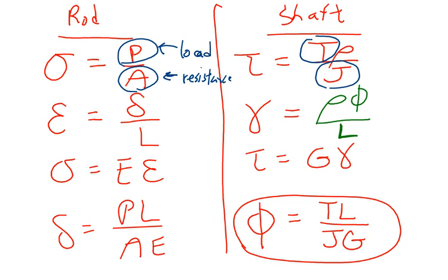Unlike the rod, that stress is not constant over the cross-section. We just said earlier that the stress goes from 0 at the center of that cross-section all the way to a maximum value at the outer edge, right? So that's just what rho does for you. Rho is the term that governs how your stress varies from the center all the way to the outer edge. Okay? So there's another equation that's usually how shear stress is calculated in the shaft.